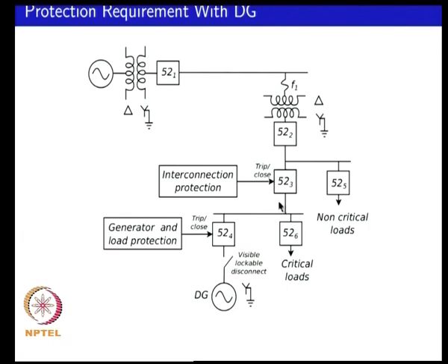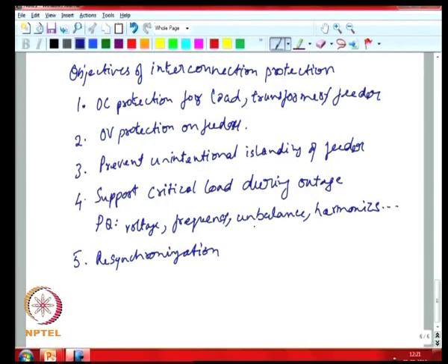Then you can close this particular breaker and resynchronize to the grid. So, resynchronization would also be required at the interconnection protection.